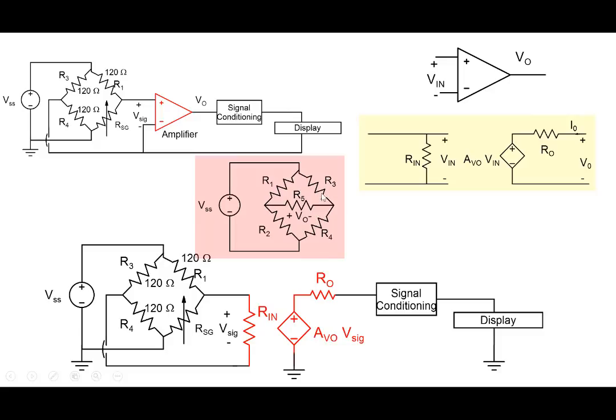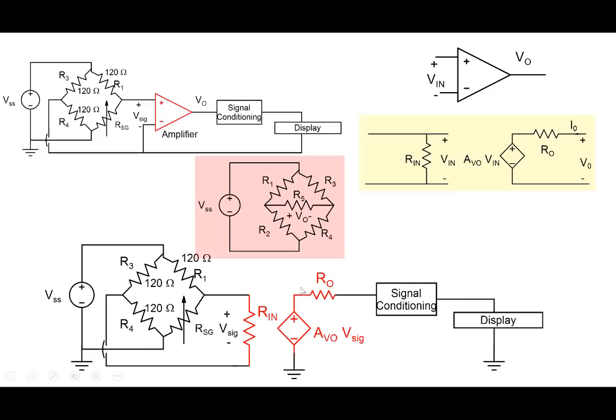But if it is not balanced, then there will be a voltage across it. So we'll see that at other places also, this Wheatstone bridge here. So the point is that if there are amplifiers in my circuit, I need a voltage controlled voltage source here, a new element.